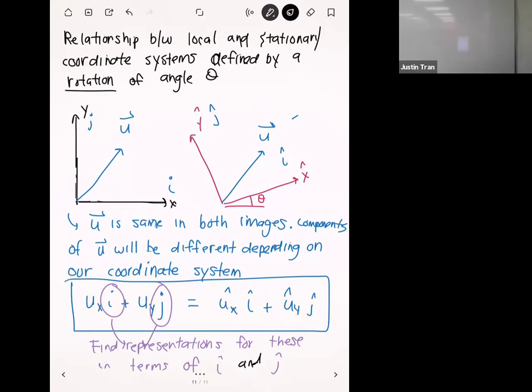So I was playing basically just a weight mode on top, but it seems like it's kind of just tilting one way, which doesn't make sense because it's a symmetric mode. I didn't get a chance to really examine this, but I think some of the connections in the solid element mesh are not properly defined, because this CAD model is not the cleanest in the world. Some parts just weren't close enough to each other to form a good contact. So some parts are bonded, but some are not, and that's why you get this weird asymmetric displacement distribution.